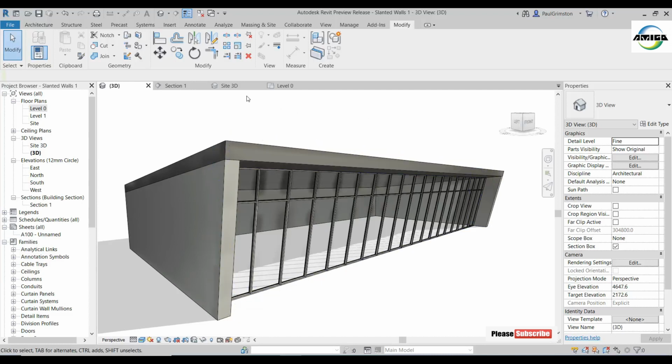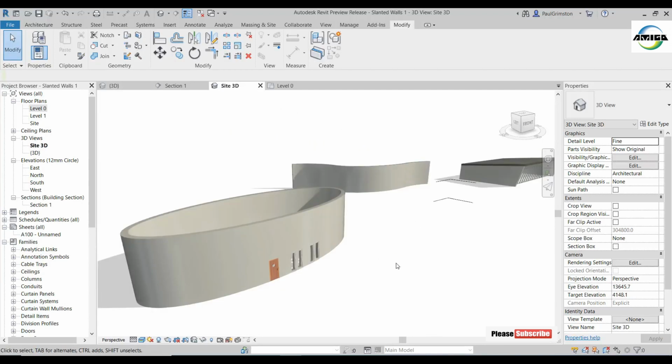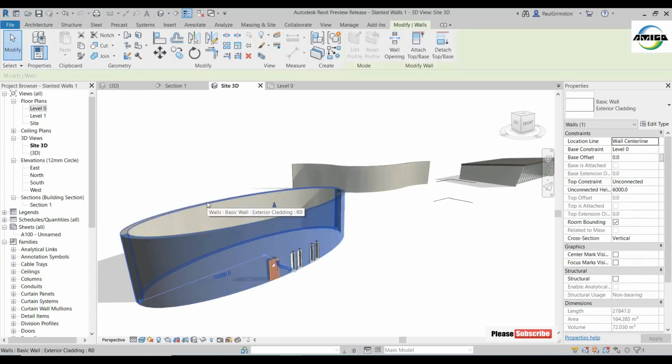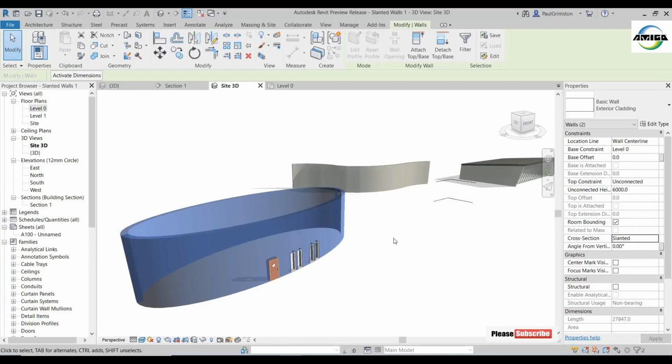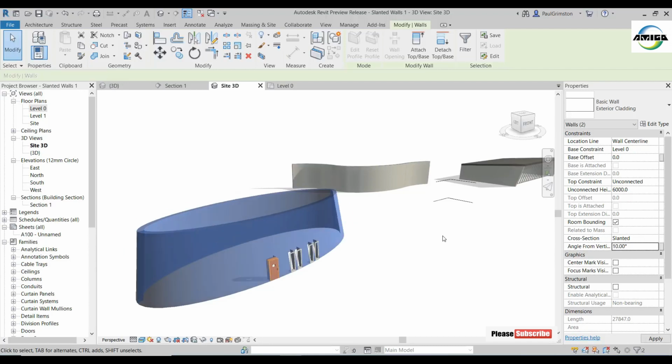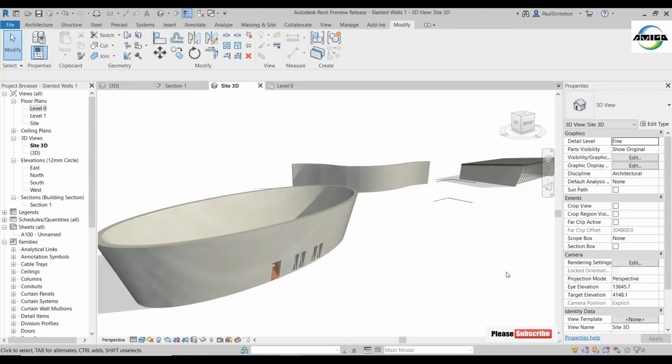It works with all of our wall types in here. So coming over to this view, even with the elliptical walls, new in the previous release, 2020, we can still choose these and again just swap these to be slanted. One slight thing we've noticed sometimes is it doesn't always go in the angle you expect. So putting 10 degrees in there, I was expecting those to lean out, so I need to put a minus number in there in order to get those working in the same way.